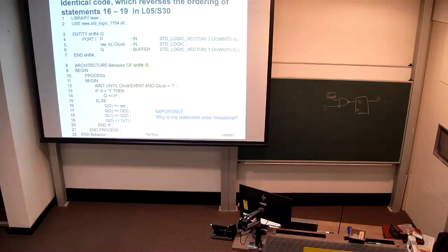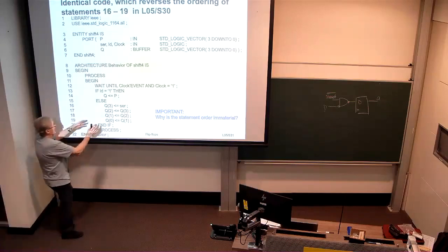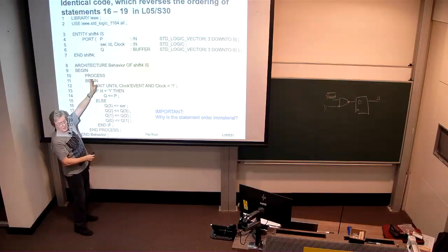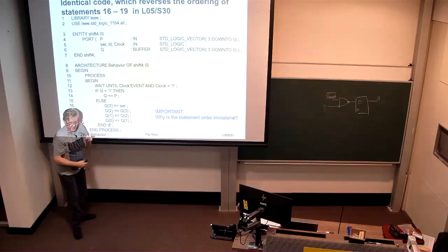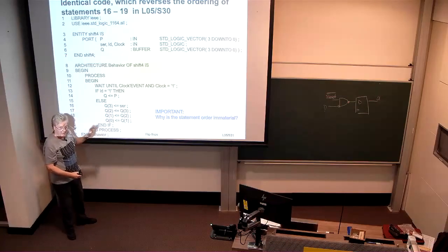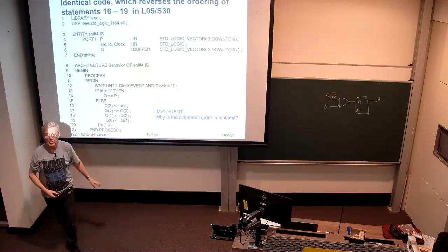So importantly, the value that a signal has internally to the process is only the value that it had when the process was entered. The value that gets written to a signal when you leave a process is the only one that gets committed at any point in time.